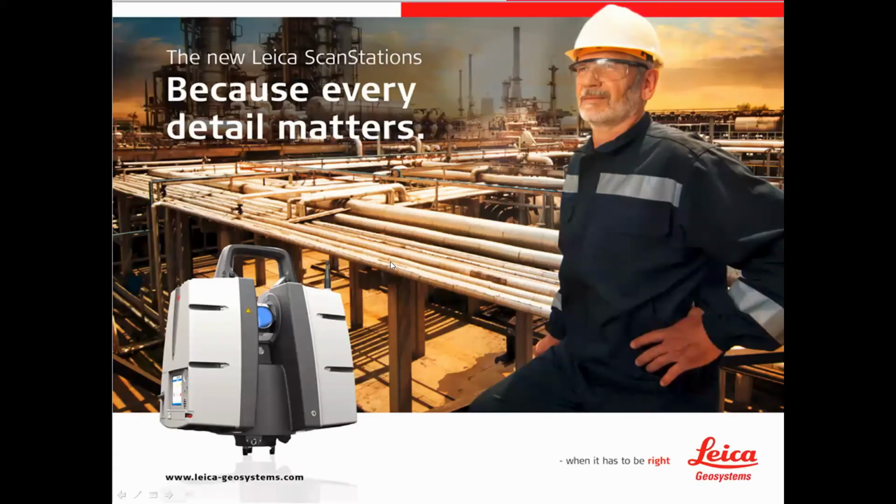So I have chosen my P40, P series. There was a P30, P40, I don't remember, for several reasons, because it is a topographic laser scanner. Topographic means that on board there is, remember, this is very important, the vertical sensor, a dual axis compensator sensor that guarantees the vertical Z, and fixes the point cloud as vertical.